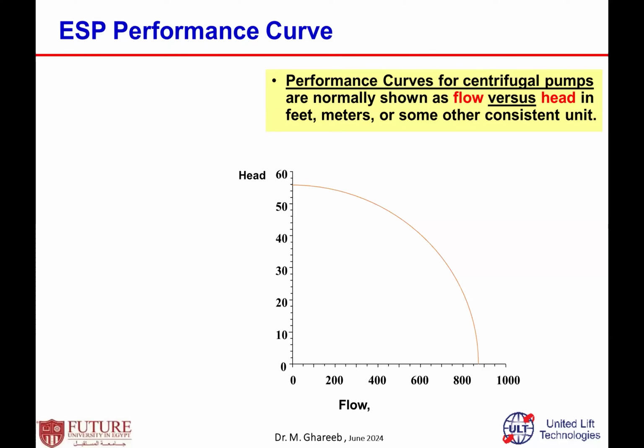Since this pump is a centrifugal pump, each pump has a performance curve related to the pump itself. The performance curve for an ESP centrifugal pump normally shows what? Head against flow. Each centrifugal pump has this performance curve, which shows how much head is generated against flow rates.